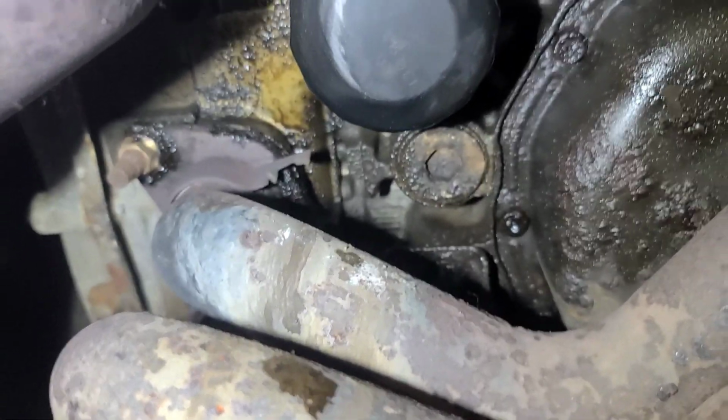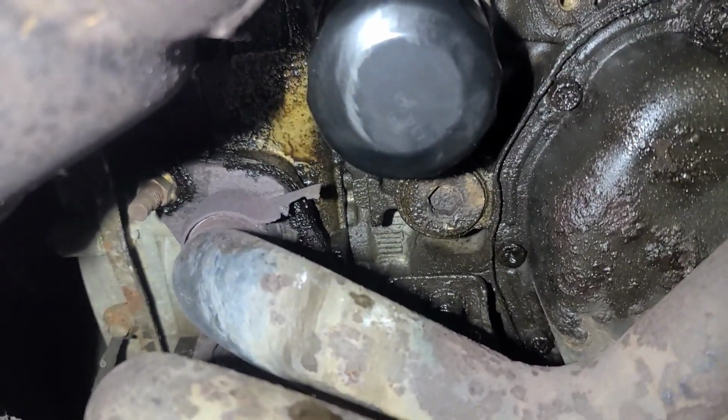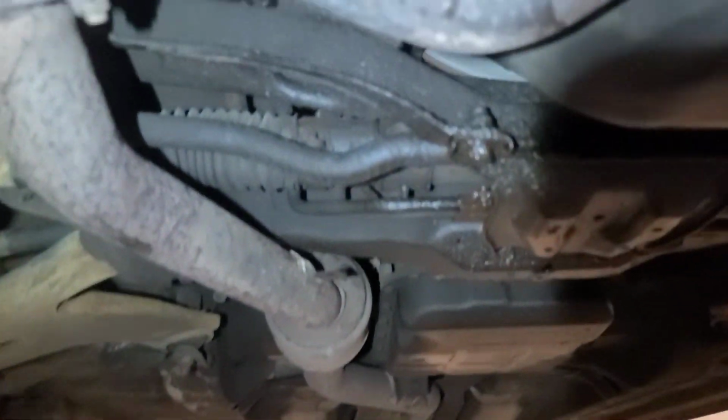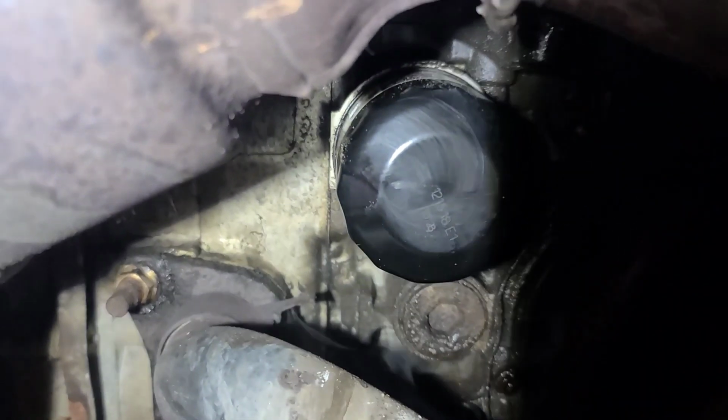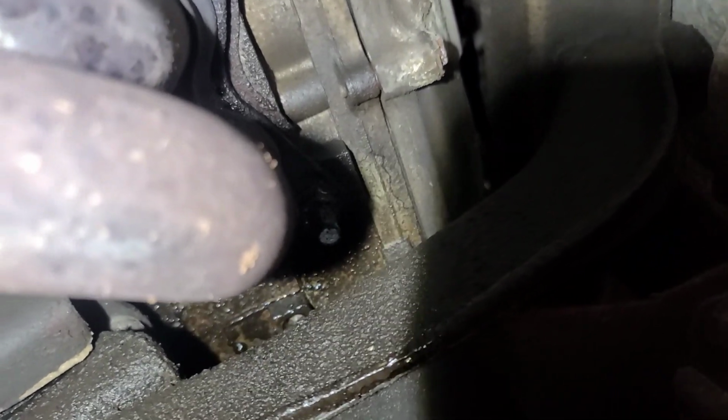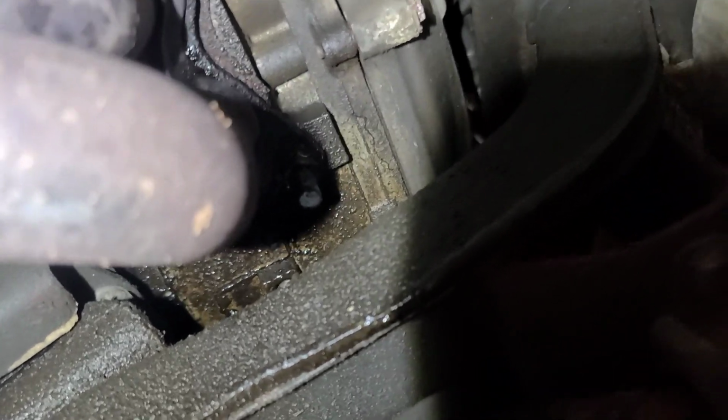I'm going to clean that off after I put oil in it and run it and see if it drips from the head gasket surface. So we got fresh oil in it. It's not leaking profusely, but if you look at this side, it's also wet in the same general area between the head gasket and the block, or the head and the block.